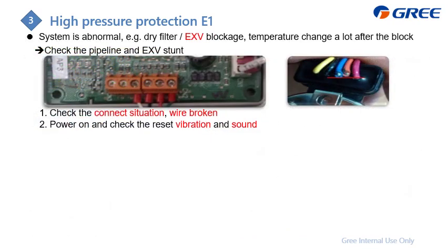As for the blockage or the sting, just focus on the dry filter and the EXV, especially when the temperature changes a lot, then there must be a blockage. And here is how to check the EXV. First is to check the wiring to the EXV control board, and then to check the wire of the EXV, in case it is an open circuit.